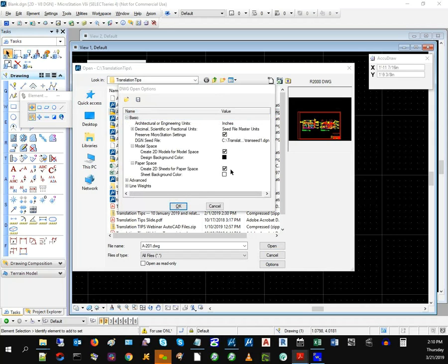and one of the first things that you run into is that in MicroStation, for people that are doing civil work for the most part, you've got a U.S. survey foot that is a standard unit in MicroStation, which is used by departments of transportation and related organizations and their contractors as a result. But AutoCAD doesn't really have a difference between a U.S. survey foot and a standard imperial foot. You're just using master units, so it's either foot, survey foot, or whatever you designate the file to be. But when you're opening a DWG file that's done in feet, and you want it to become U.S. survey feet for use in MicroStation,